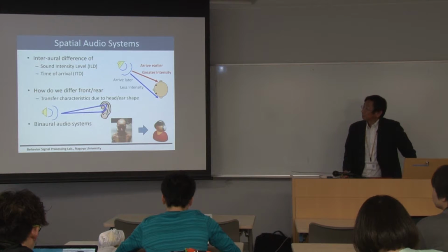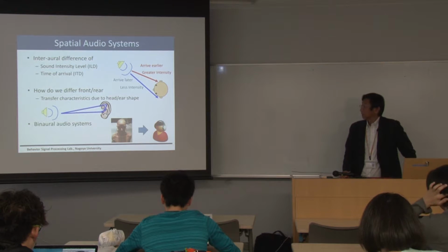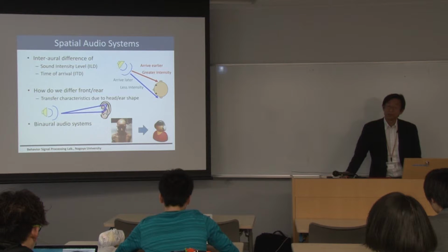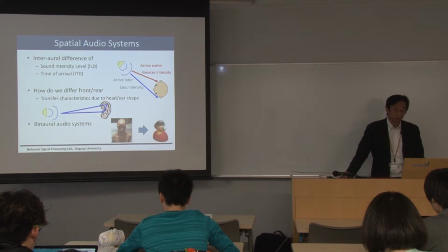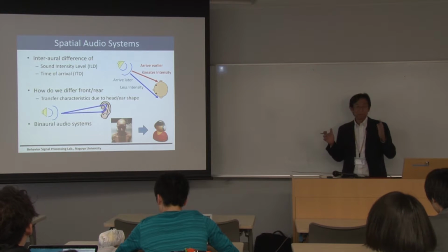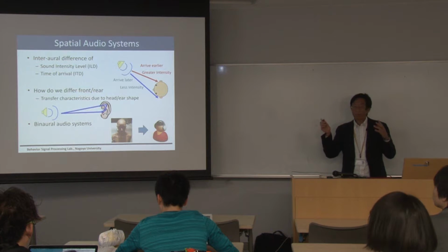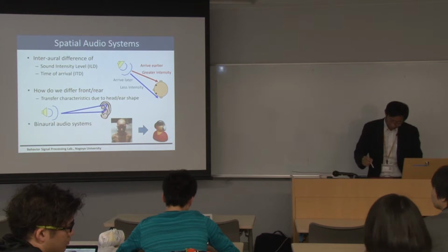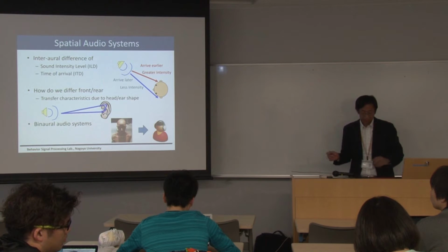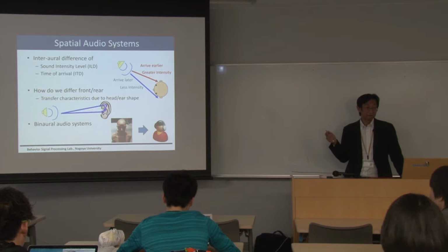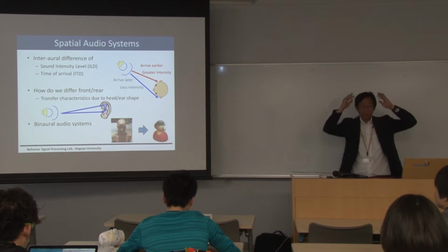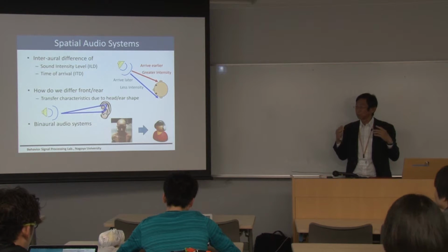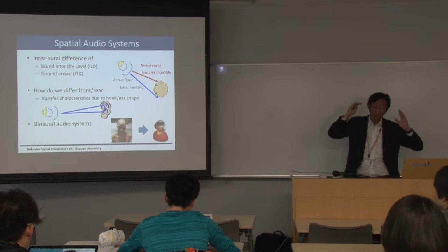The other technology that is indispensable for building spatial impression audio is the HRTF, or the technology so-called transaural audio. Do you know why people can perceive the direction of arrival of the sound? One big cue is the difference of time. If the sound source is located on your right-hand side, then your right ear will get the signal earlier than the left ear. So your brain does the signal processing, comparing the difference of the two signal phases, and then you can perceive the difference in location.